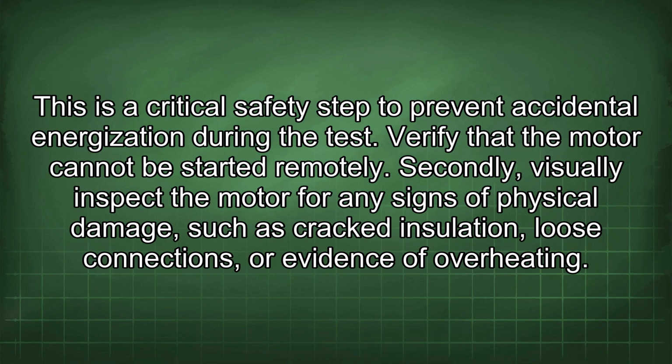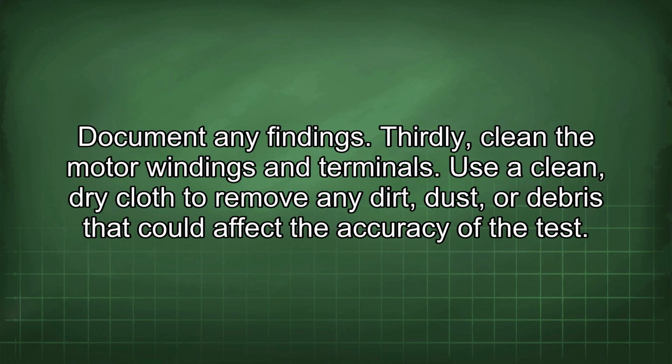Secondly, visually inspect the motor for any signs of physical damage, such as cracked insulation, loose connections, or evidence of overheating. Document any findings. Thirdly, clean the motor windings and terminals.